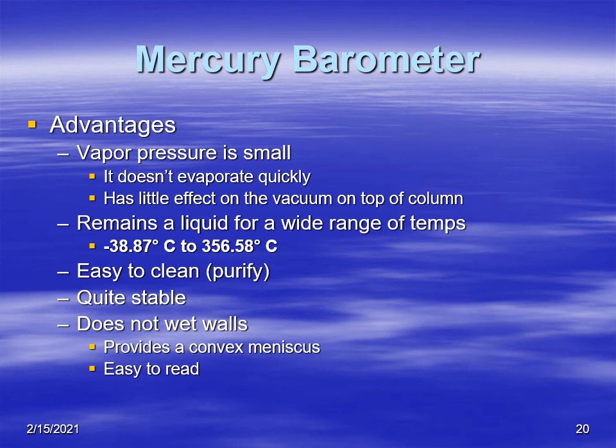Also, mercury is relatively easy to clean or purify. It's quite stable, and it doesn't cling to the walls of glass, so you get a nice convex meniscus, which is the top of the mercury. In other words, it's easier to read and interpolate. So that's a little bit about manometers and also mercury.